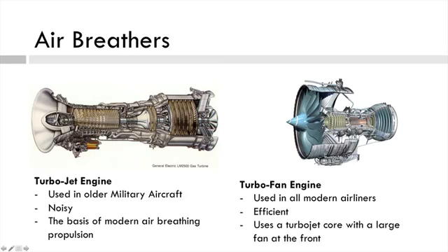This section here is the compressor. Then we've got a combustor, a turbine, and then an exit or a nozzle. The way this generates thrust is by taking in air, compressing it, adding some fuel, some heat, taking some energy out to run our compressor, and then firing very quick gas out the back.